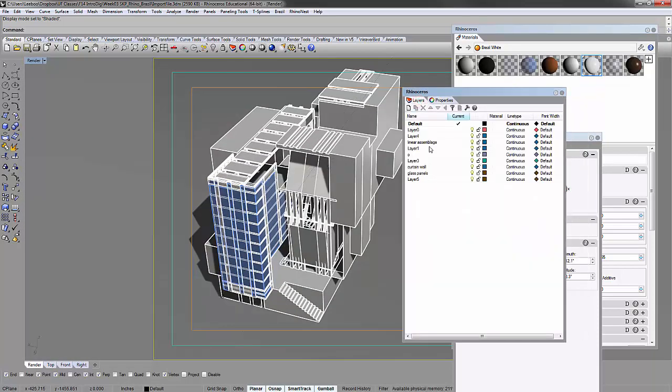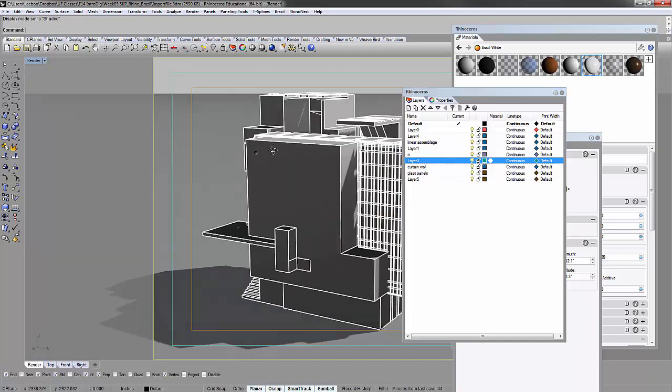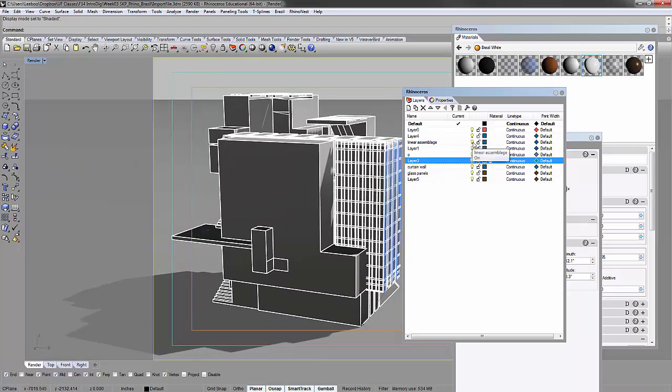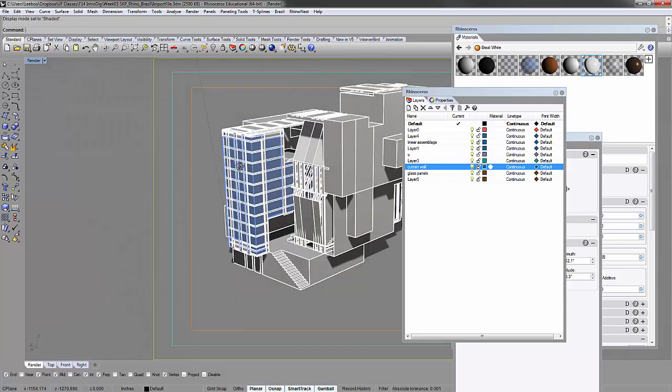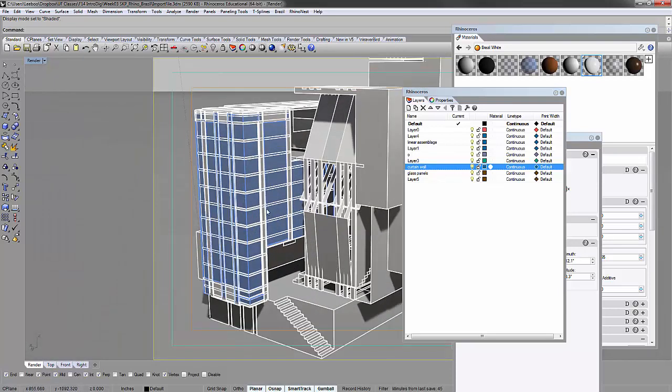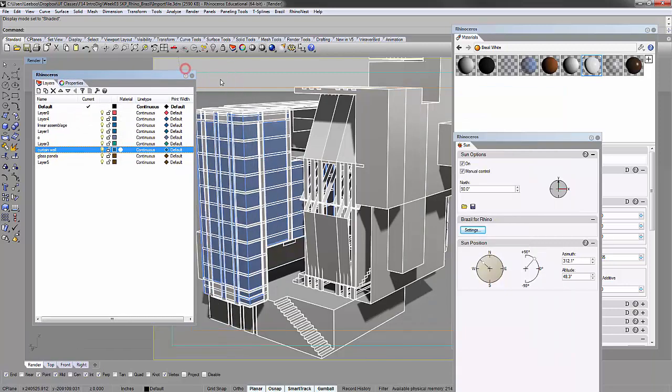So that's why in particular it's important that you organize things well by layer, so you know exactly which things are on what layer, and you know what you want to do with them. Although you'll find that after you explode them, you might have to do a little bit of rearranging to make sure that things are going in the right direction or in the right layer. So you'll have to spend a little time doing that, right?